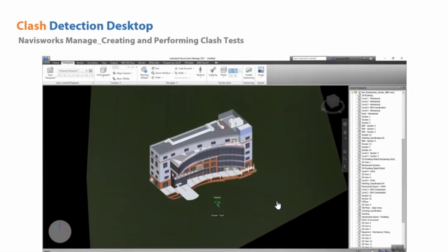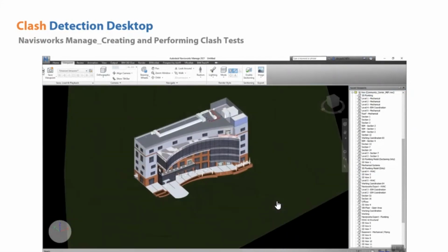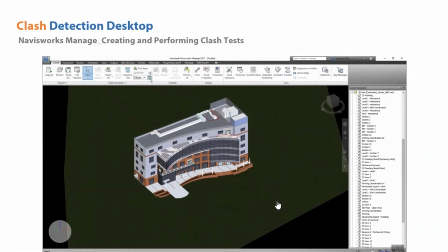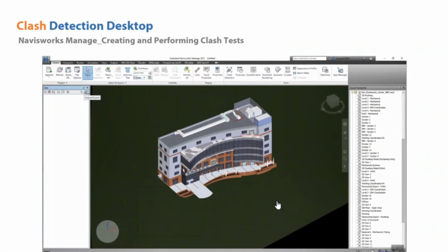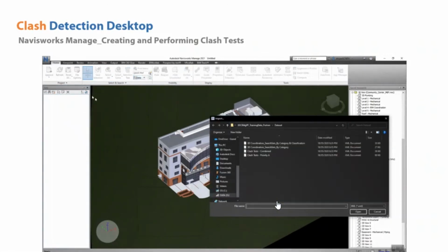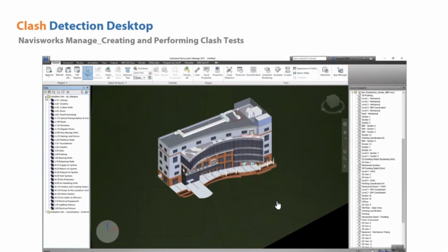And then comes the power of creating sets inside. So basically, in Navisworks, we can use the search sets using the Manage Sets option, and we can import the search set as a template to be used for any of the projects involved. And once the search sets have been added, this is very dynamic. You can select the elements based on specific conditions or values defined inside the clash test. Selection of specific elements based on specific values.